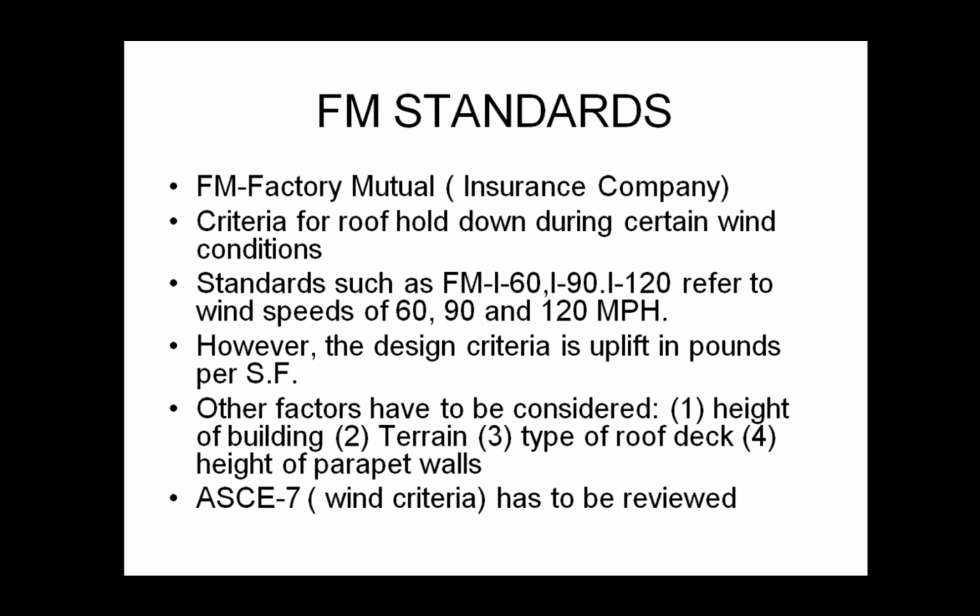And 60 is a fairly weak wind speed. Every year, past 10 years have probably broken days with 60 mile per hour winds. So, 120 is more typical. That's hurricane rated, and that's usually what you'd want for the minimum.